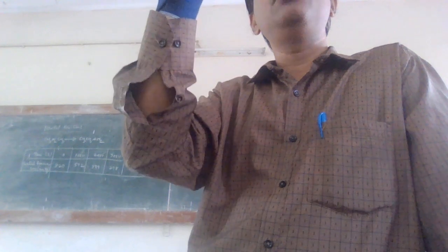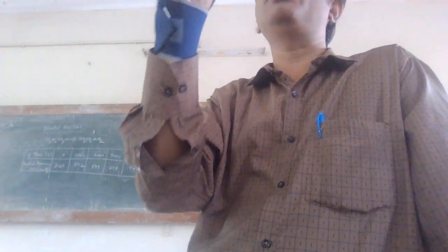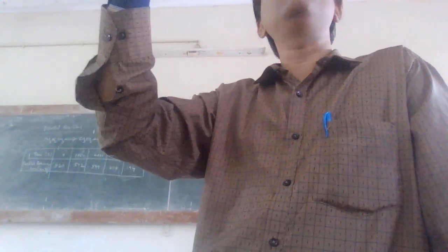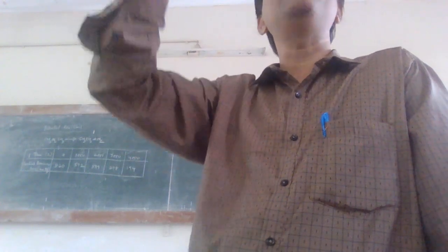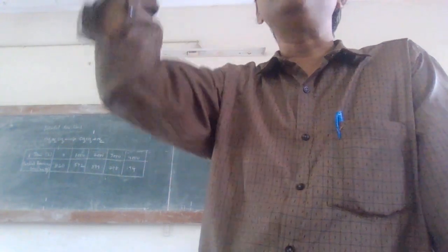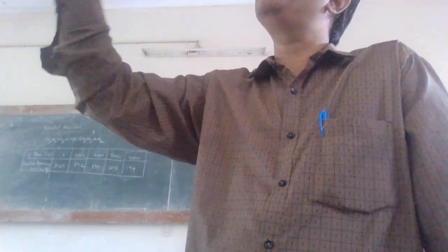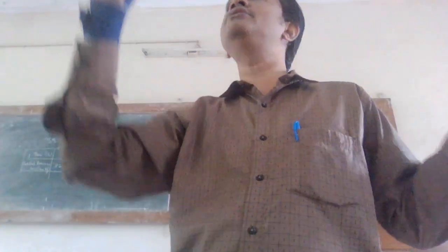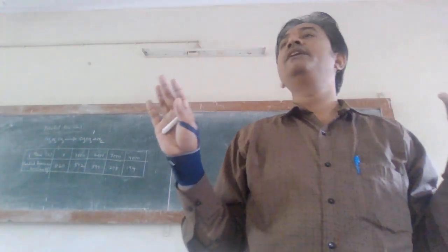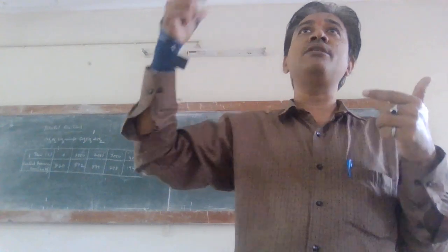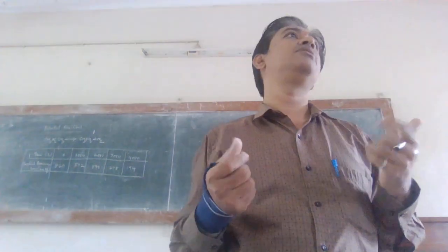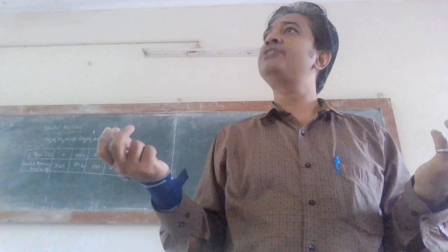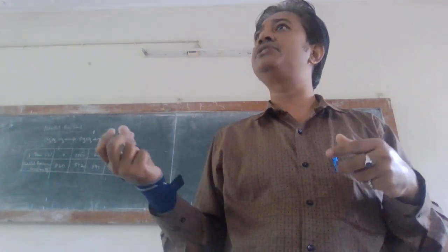Is it not? The previous problem what you have done? In the previous problem, at time equal to 0, we got the CA value, that is CA naught, and then the CA values. So CA known, CA naught known, if you assume first order, minus ln CA by CA naught is equal to K into t, t known. So you have estimated K, and all the K's are almost constant, means the assumed order is correct. That's what we proceeded. Now what is the difference between the previous problem and the problem I asked now? You might know the conversion of partial pressure to concentration.